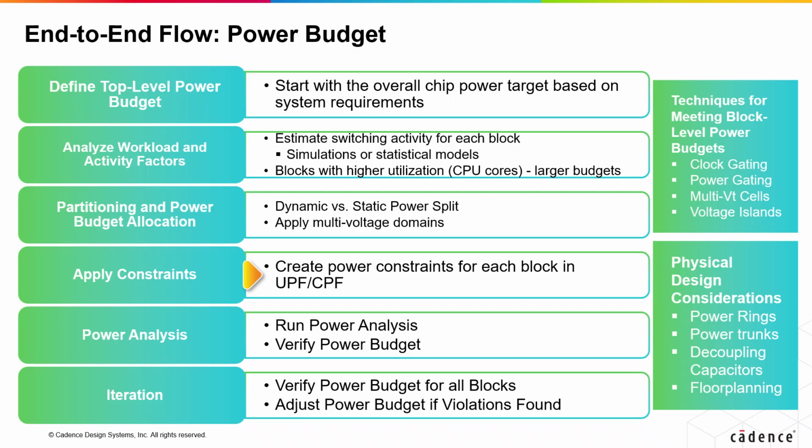Physical design techniques such as clock gating, power gating, multi-VT cells, and voltage islands are employed to meet block-level budgets, while layout strategies like power rings, trunks, decoupling capacitors, and careful floor planning ensure robust power delivery and minimize IR drop. Power analysis is an iterative process.